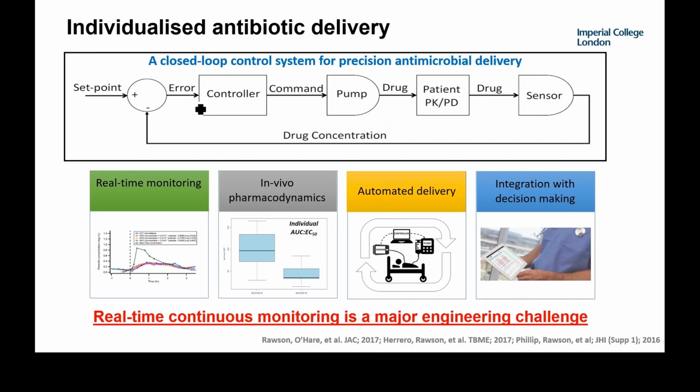So what we need is some sort of sensor to feed a drug concentration, compare it with a set point, calculate the error, have a PID controller typically here that's then driving a pump that makes predictions as to how fast the infusion needs to be to get the optimized dose, which is responding now to the unique patient's pharmacokinetics and pharmacodynamics. So the absorption, distribution, metabolism, and excretion by the patient, and whether or not the patient is even responding.